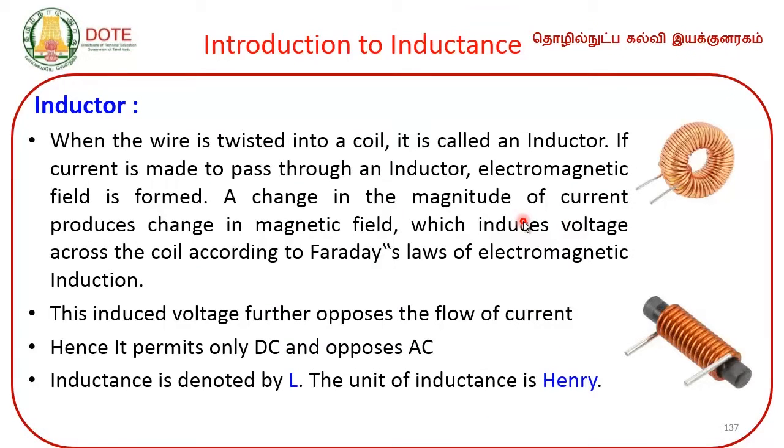In and around the coil we get the dynamic flux; the coil is fixed, but the flux varies. Whenever there is movement between the conductor and the magnetic flux, EMF will be induced on the conductor. This is Faraday's law. The induced EMF, the counter EMF, opposes the cause, that is Lenz's law.